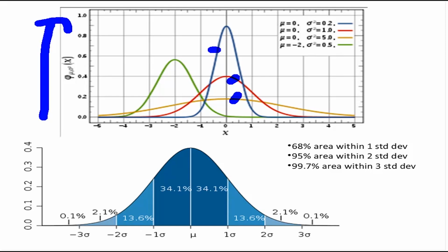So yes, there are a maximum number of devices at 65 nanometer, but a lot more devices are showing channel lengths which are greater than 65 nanometer and less than 65 nanometer, and the curve is pretty wide, right? We don't want that. We want a curve of this kind, which is sharper, less wide, which has less variance, less standard deviation. This is what manufacturing tries to control, right?